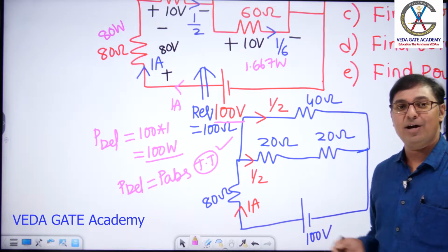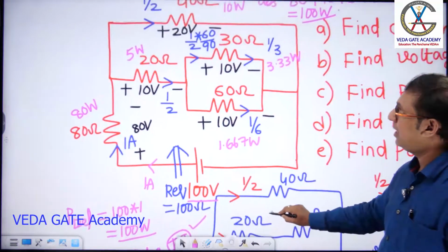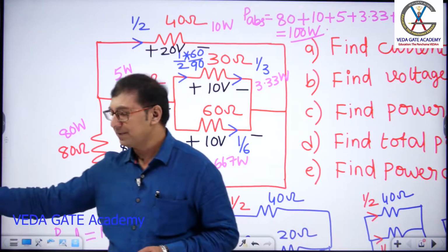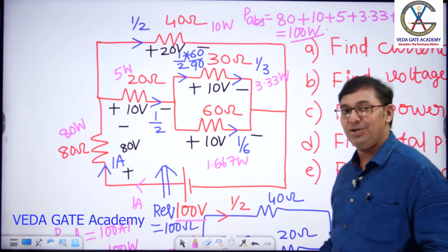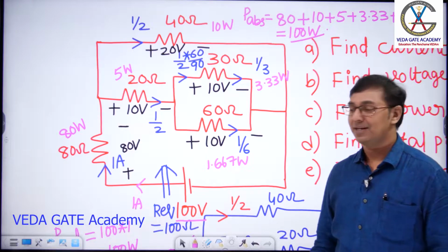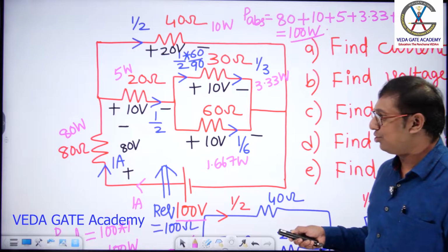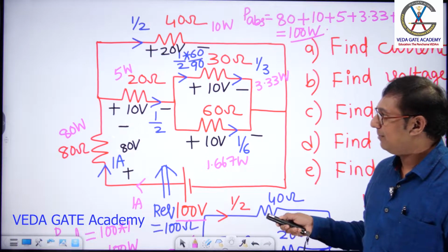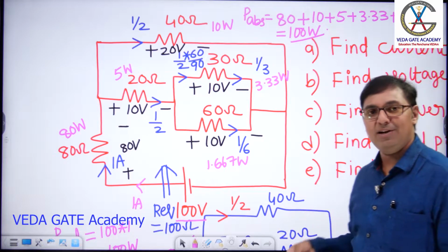Tellegen's theorem is verified. Sir, are the answers we got correct or not? Yes. Sir, the beauty of the network subject is that you can verify your answers on your own with the help of basic laws. What are the basic laws? Kirchhoff's laws. KVL, second statement: 100 equals, start positive, go to negative following the KVL sign convention. 100 equals, what is the voltage here? Plus 80, plus 20, 100 equals 100, KVL is matching.